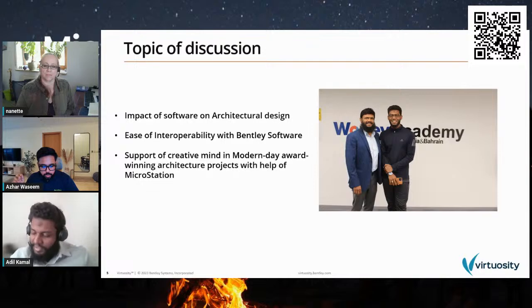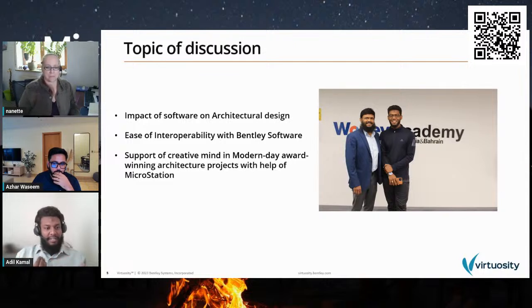Okay, in this I'll be genuine. As an architect, we try to focus a lot on energy, and the major component of energy is natural sunlight and natural wind ventilation. So we have something called passive design, and we consider sunlight in all kinds of design. Let's say we design facades for a building as a skin, and we try to invite the east sun, which is the best sun in the morning, and avoid the harsh south sun. This is how we consider it in design itself.